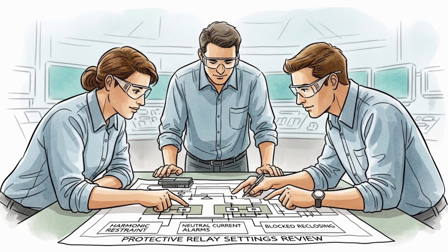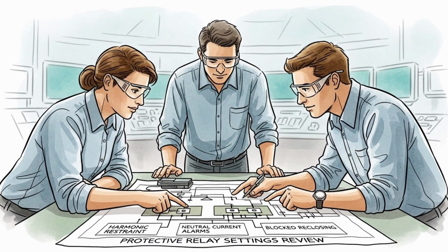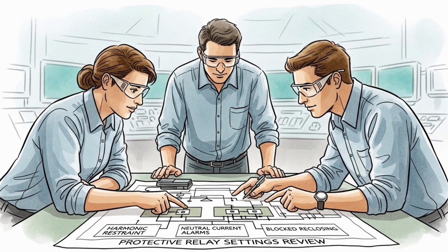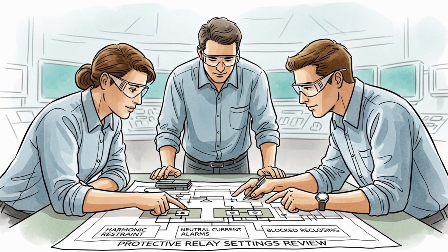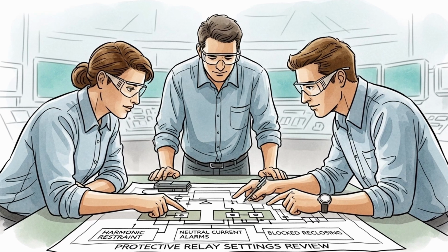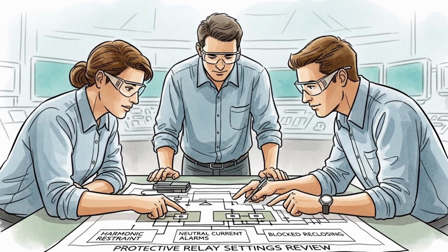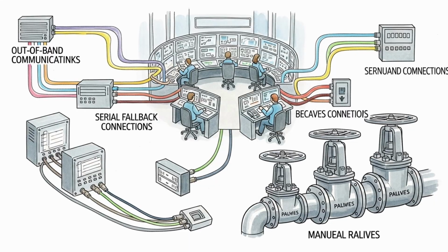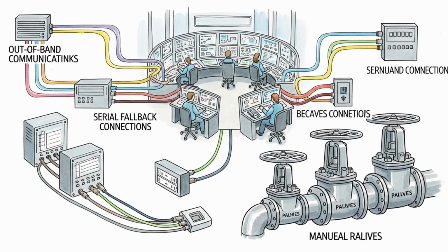Operators update drag coefficients, perform more frequent orbit determinations, and schedule small burns to hold altitude. Smaller satellites with high area-to-mass ratios are most affected and may re-enter if margin is low.